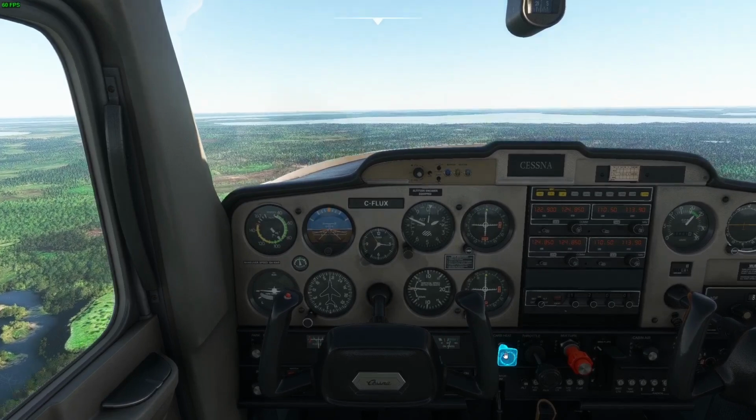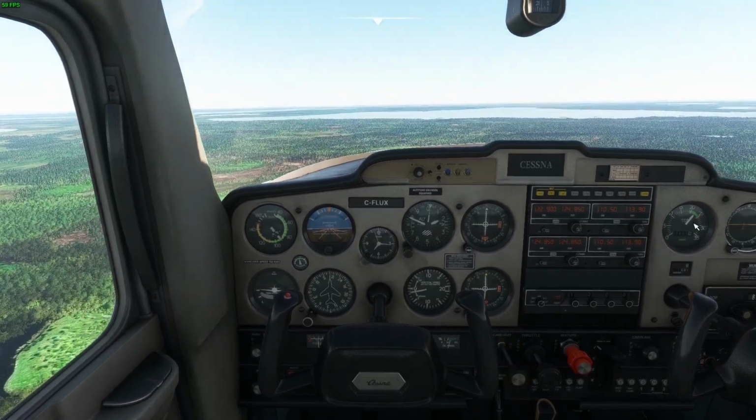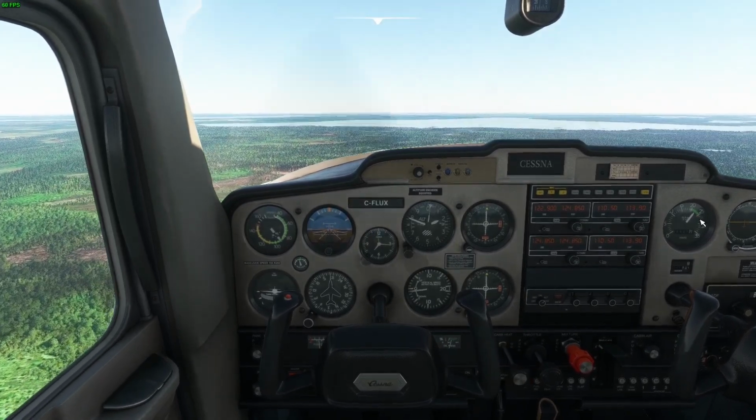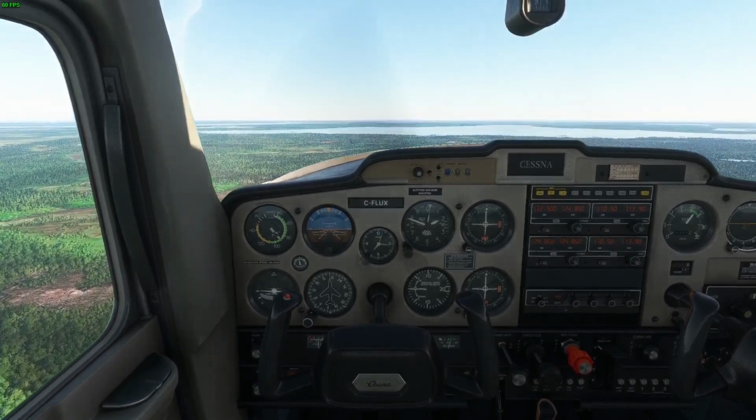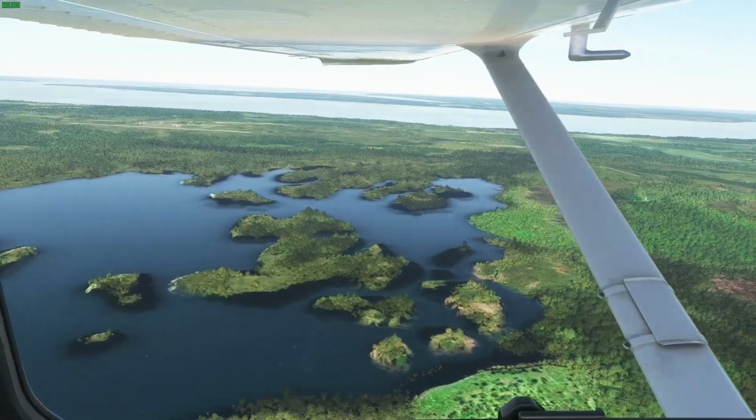Okay, things have settled out. RPM's good. Now we're mid downwind. We're getting ready to land. So pull a carb heat out and leave it out until we land. Okay, because we're about to pull power off and descend.